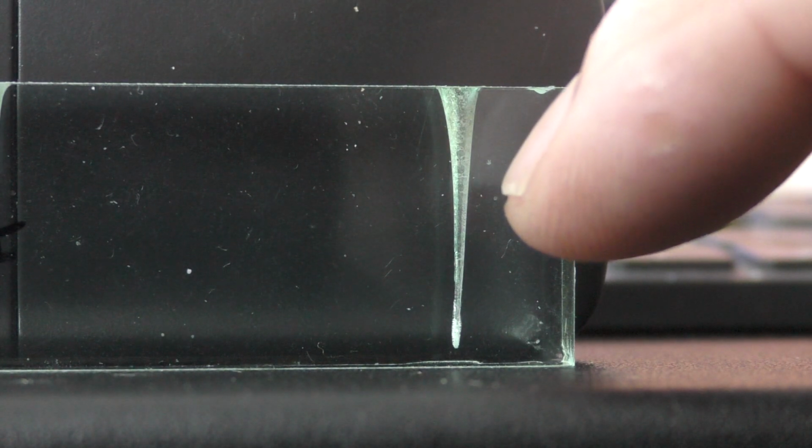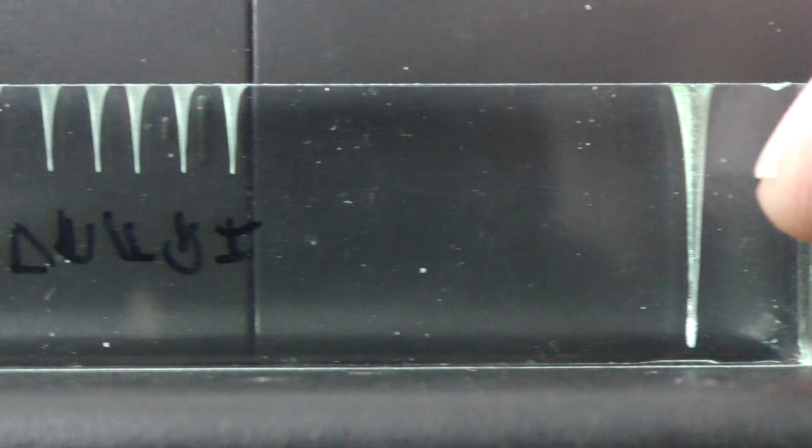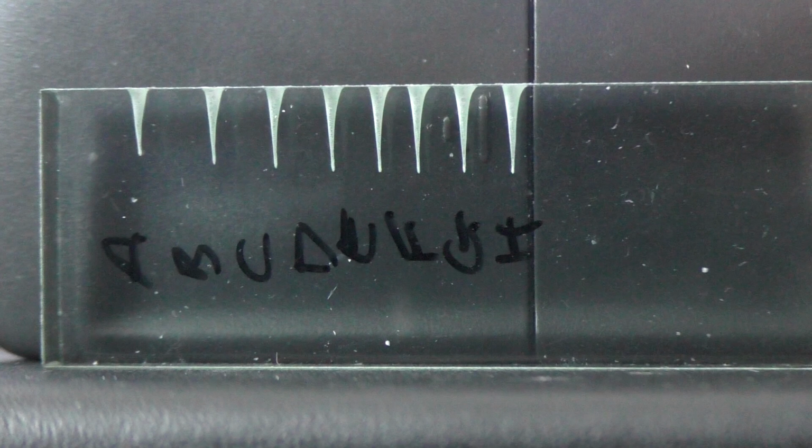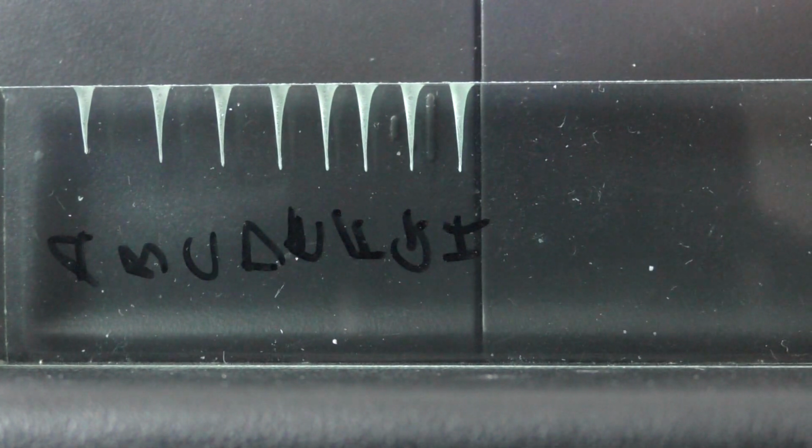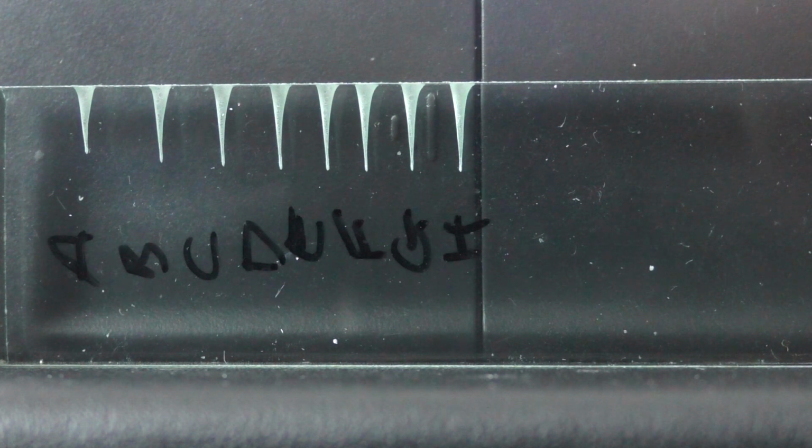So just to verify before we start, I tested the beam right at the centre of the machine where we've got the smallest beam. And then I popped the 7.5-inch lens in, and these are the results. The beam is quite thick and the penetration is probably twice as much as I've achieved before. As you can see, we've got A, B, C, D, E, F, G and H there. Well, A was done at a focal distance of 112. B was done at 102. C was done at 92, and then they run 82 all the way down to 42 as the last one.